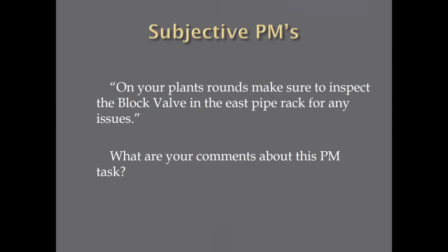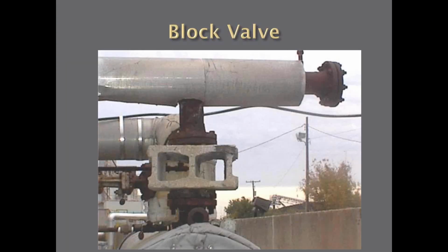What about subjective PMs? A lot of times at our plants we have these subjective PMs that say, check the pump or check the valve. So here's one I put in here just to jog your minds a little bit. It says on your plant rounds, make sure to inspect the block valve in the east pipe rack for any issues. So what are your comments on this PM? Inspect the block valve. Is this not a block valve? As we look at that, it's a block. It's a cinder block. Is it a block valve? Well, what is the definition? What are we inspecting here? Kind of a joke slide, but again, it stresses the point of what is our PM trying to find.